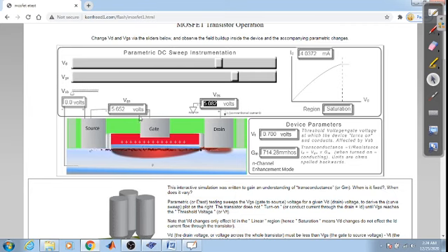If you reduce this voltage, or if you make this as 0, okay, now let us make this as 0, what happens? Automatically it is turned off. There is no flow of current. Okay, so this is the operation of MOSFET. So by applying the voltage to the gate and source, between gate and source, it will be turning on the MOSFET. So just look over here, so it is turned on. Okay, so this is the working of the MOSFET.